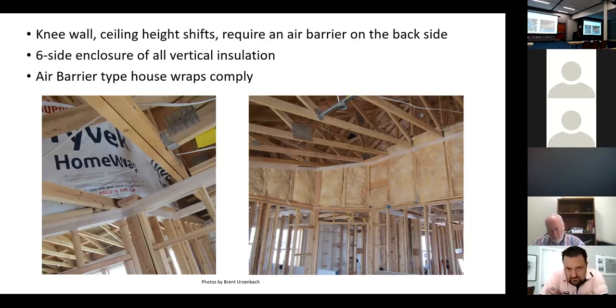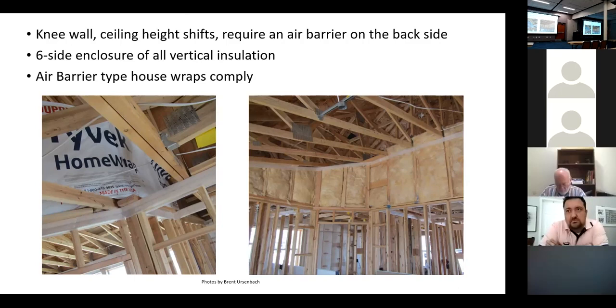Right? Well, and that's my question there. So this loose fill insulation in the ceiling, you're saying you don't need that weather or that barrier. But so why would you need it on top of that back? Because of the rising, the convective flows. We don't get convective flows like this on a horizontal. It's what we have, a surface that either heat rises or the cold drops, the cold air drops, or the warm air rises. That's where it comes from.